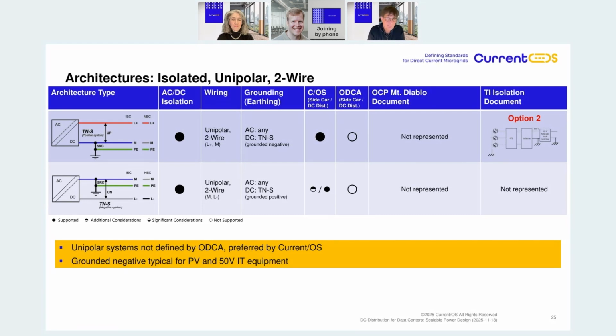That is mainly done because you want to prevent corrosion effects on the L minus, on the electrical installation. But that results in possible corrosion effects in the mechanical structure. If you go to the first one with the positive system, with the positive voltage, technically you could have corrosion effects on the L+, but you have less risk of corrosion on the structure.